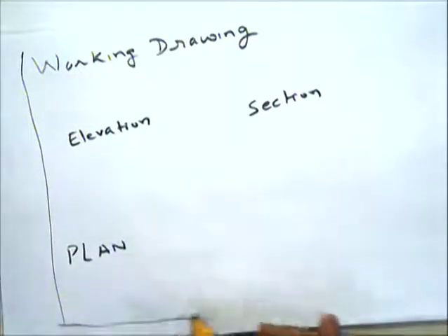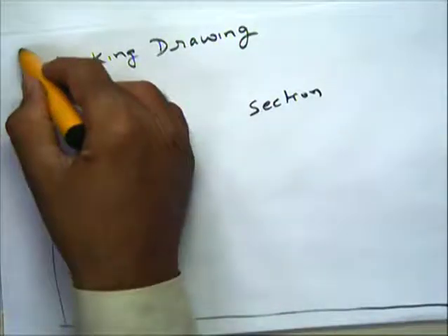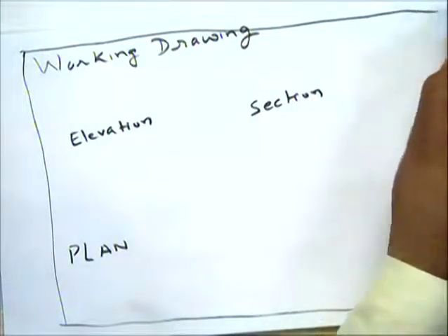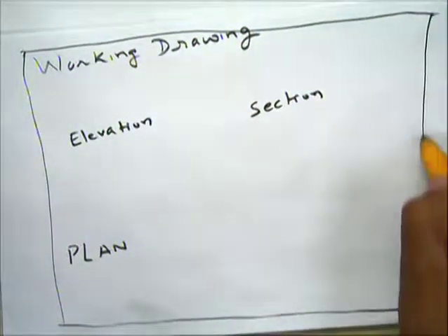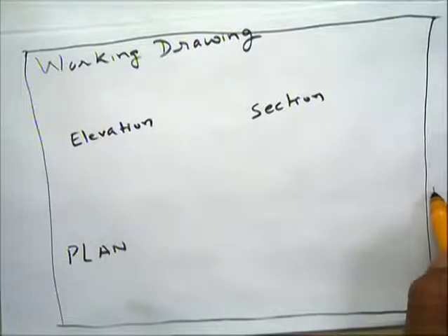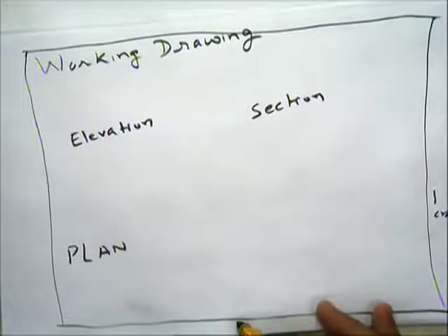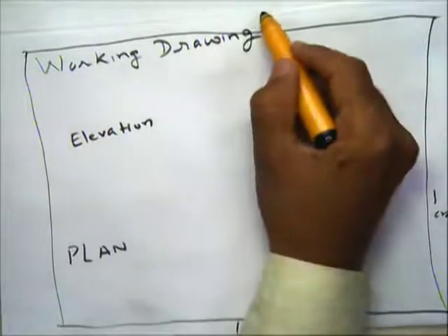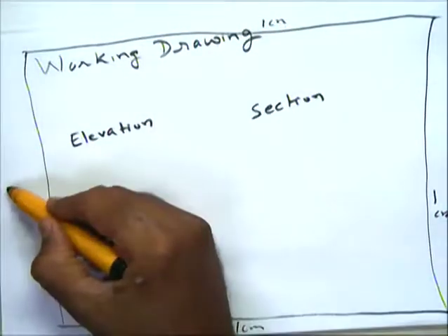Before starting the drawing you have to put the margins. On the left edge you have to put a margin of 4 centimeters, and for the remaining sides you have to leave a margin of 1 centimeter. So this is the layout we have already seen.